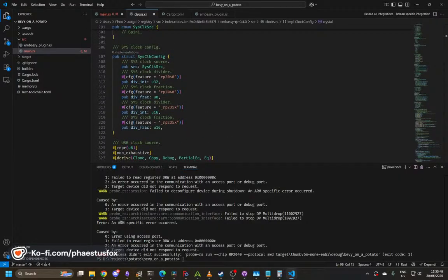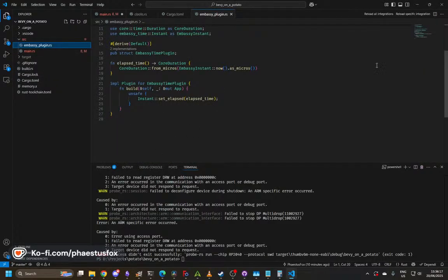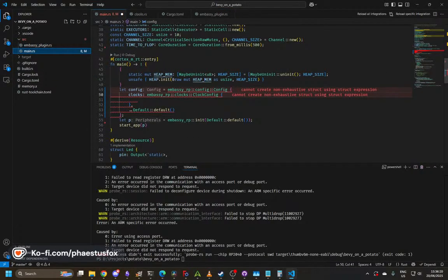So they have examples. I should probably go to the Embassy website and look, or their GitHub. Funnily enough, every time I go to GitHub, it's the default one it goes to because I went here so often when I was trying to develop this previously, before Bevy was compatible, and I found Embassy really hard to use because I'd keep static references to things and be like, well, I know I'm not going to be using it mutably twice, because everything was ref cells and stuff like that, just to get around the borrow checker. Whereas Bevy lets me stick a resource in that holds the bus, and then I can just pull the resource out when I need it, and I lose all the async stuff, but to be honest, most of the stuff I was doing did not need to be async.